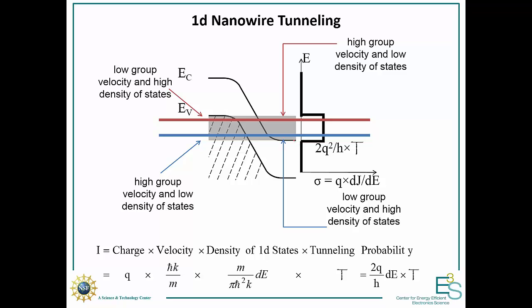One is that our conduction band and valence band only overlap in this regime, and so current can only flow here. Naturally, what we want to ask is how much current is flowing at each energy, and then integrate over that to get our total current flow. To start, let's assume the valence band is full and the conduction band is empty, so we can have tunneling occurring at all of the energies where they overlap.